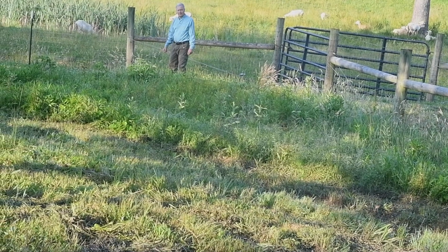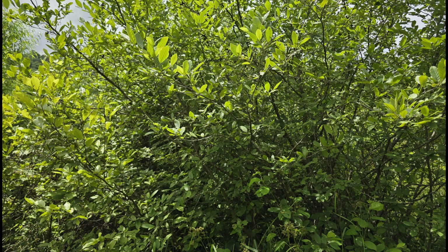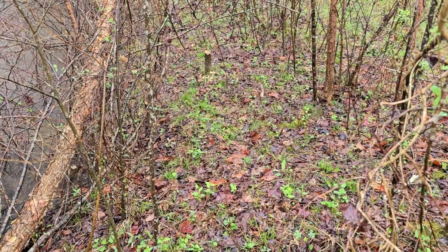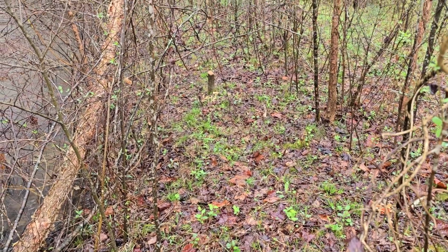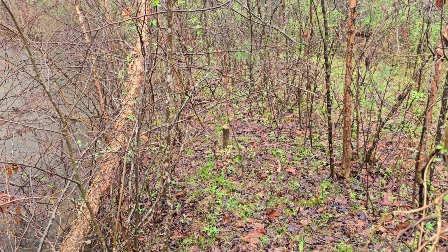It's in good condition. It's very difficult, if not impossible, to inspect a dam that has not been mowed. The trees and shrubs you see growing here, they're growing on a dam that has not been mowed for many years. The dense growth of trees and shrubs makes it almost impossible to find holes, breaches, or seeps in the dam. This dam can no longer be mowed with a tractor and a bush hog because the trees are too large a diameter to ride over with the tractor.